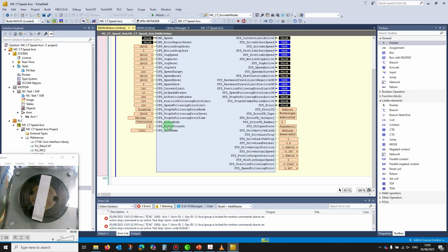Okay. You've got the ability to focus on an individual MC type function block by saying pick this number. So if you've got an error and then you end up with a number for that function block, you can take that number from here, put it here, and then it will focus on that individual function block when it has a problem as a part of fault finding. So you've got a flag here that says, is it an error?